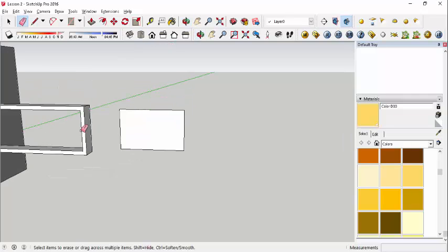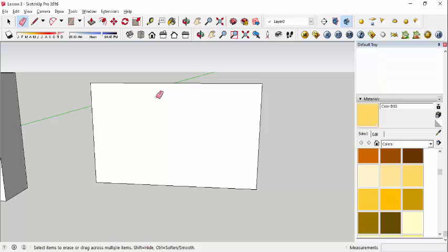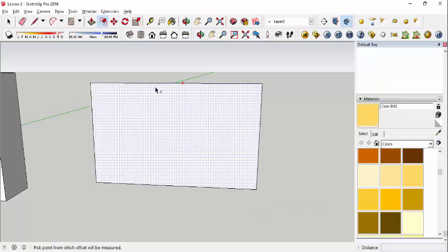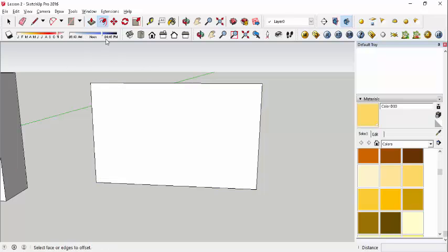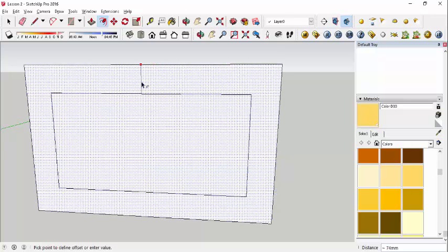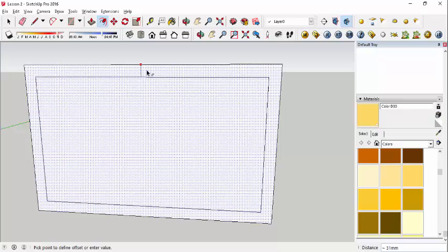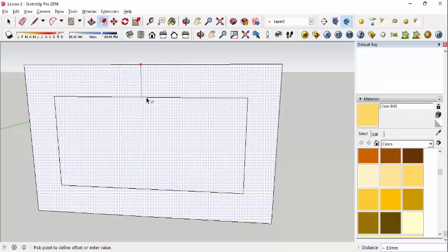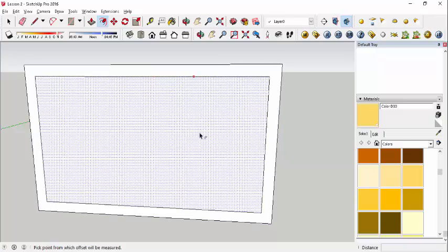Okay, so if we use 40 for this, the inside framing should be a little bit thinner. So let's use 30 or 1 inch. So offset again, not O, but F. Okay, offset, which is this. So that's F, and then type in 30. Okay, let's do that again. So F. You'll know it's already in operation if, when you click inside, it will have these little dots. So click inside and then drag. If you start to drag it, you will see the lines coming in or out. So you want it to have an exact measurement, so type in 30 on your keypad or keyboard.